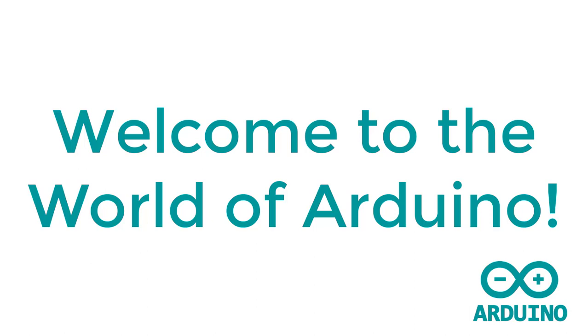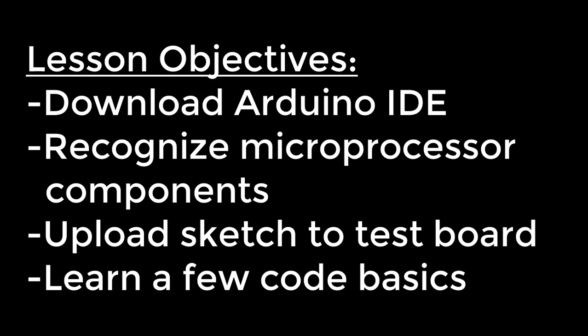We're going to start out with a simple exercise simply to familiarize yourself with the Arduino software and also the microprocessor. In this, we are going to download the software and then plug our microprocessor in. Make sure it's working. Make sure that we know what port it's going to show up on in our computer. And then we're going to upload a sketch to the microprocessor. And then to kind of play around with the code a little bit, we're going to do something simple and change the blink rate of the built-in LED on the microprocessor.